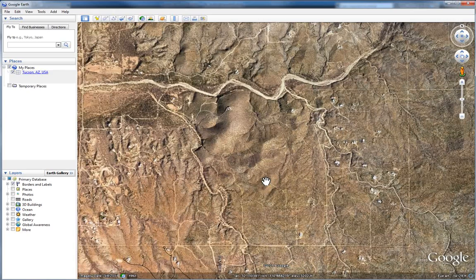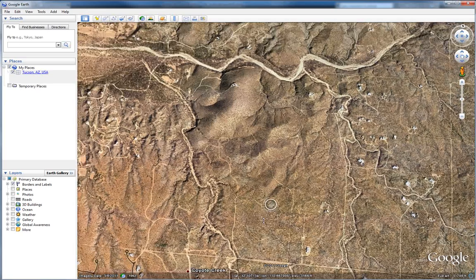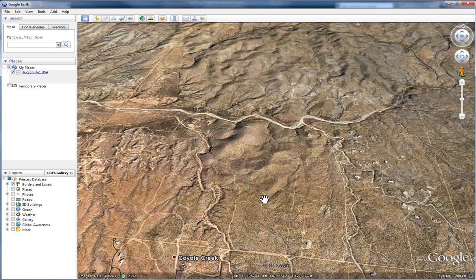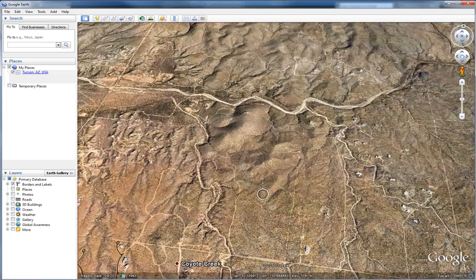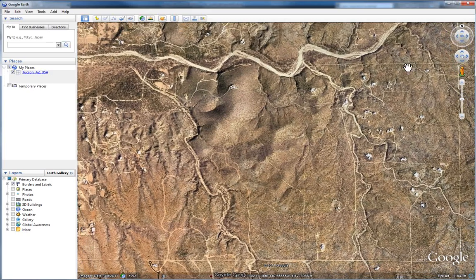Please regard that the whole area in view will be imported, so zoom in appropriately. Before importing, you should ascertain yourself that your view is orthogonal to the terrain. For that, push the central mouse key or the mouse wheel and move the mouse upwards. Another point is that the terrain should be oriented northwards. To ascertain that, please once click the N of the upper navigation element. Now we can be sure that our view is correct.